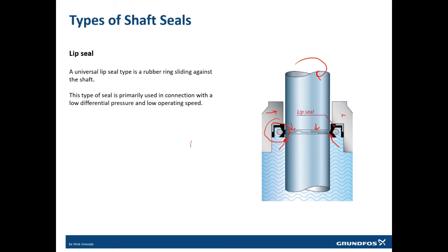After some time, this groove will finish, and once this groove finishes, the water will start going out, so the shaft seal will leak. So the shaft seal is a wear part. For any pump in the world, you need to change the shaft seal, because the shaft seal is just like the brake pad of your car. Again, coming back to the same example, this is something which will be consumed throughout the operation of the pump.